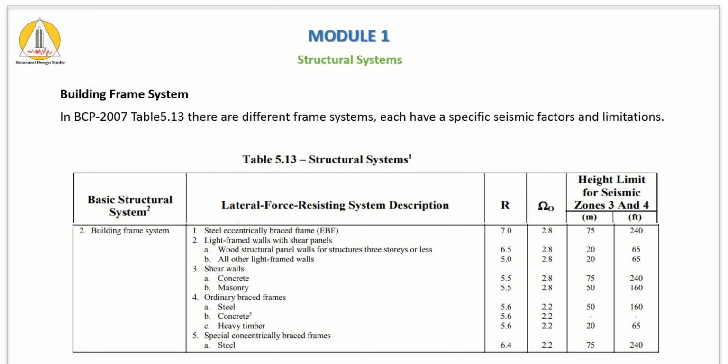But if you are using an R value smaller than 7, you are telling the software that your system is not that much stiffer as compared to R value equal to 7. So the software will give you more flexure reinforcement, because you will not follow the special requirements followed by the SMRF. Right, so this is the difference. We will talk about this in future lectures as well.